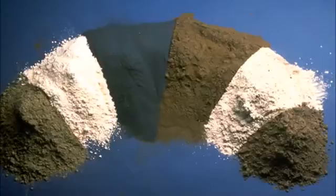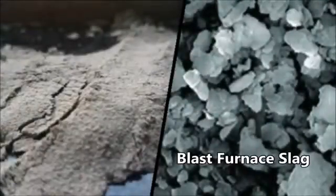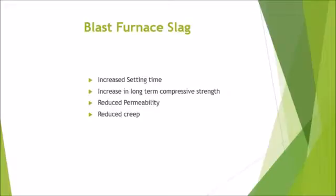There are a number of substances used to reduce the carbon footprint of concrete by replacing the clinker in concrete production. These are called supplementary cementitious materials, or SCMs for short. These include ground granulated blast furnace slag, fly ash, and amorphous silica. Blast furnace slag is an industrial waste made in iron production which can be repurposed to replace a portion of the cement. When converted to a powder, ground granulated blast furnace slag forms a compound chemically similar to cement, composed predominantly of oxides of silica, magnesium, calcium, alumina, and lime. This has a number of effects on plastic and hardened state properties, including but not limited to increased setting time, increase in long-term compressive strength, reduced permeability, reduced creep.